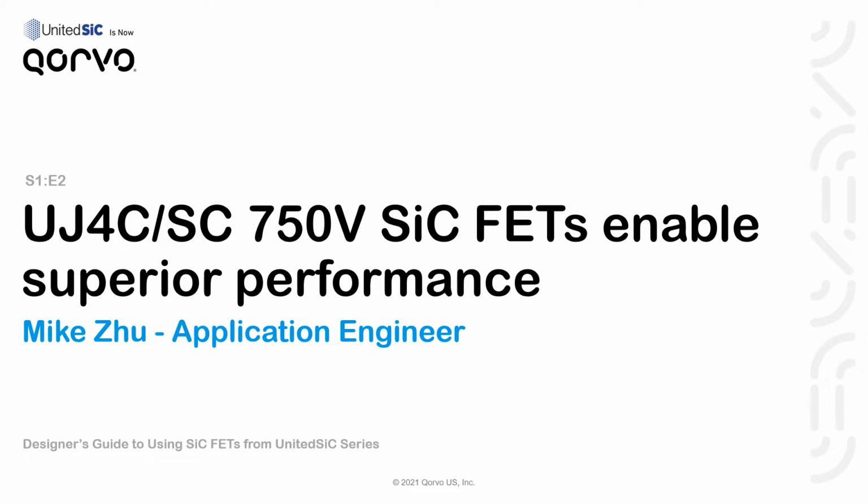Silicon carbide provides many advantages over silicon and industry adoption is growing fast. One common challenge to upgrade from silicon to silicon carbide is the noise and EMI induced by faster switching speed, which in the meantime enables high efficiency and high switching frequency. In this video series, we're going to show you where our technology stands in the silicon carbide industry and share our recommendation to overcome the challenge of fast speed.